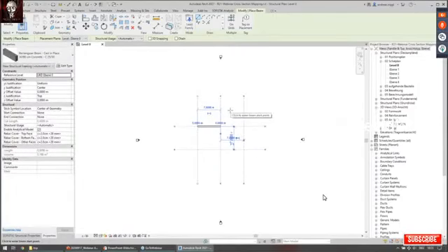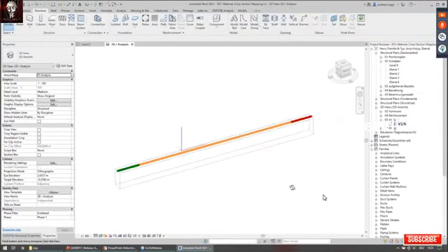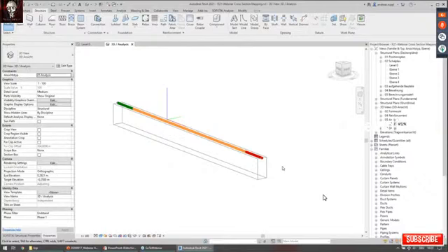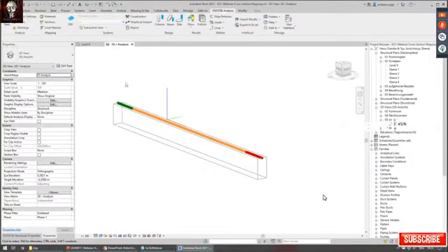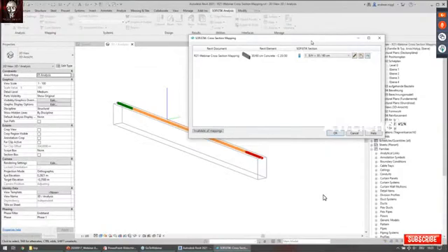So this is a predefined family which is present in the families provided by Revit, for example. And when switching to a 3D analysis view, you already see that beam within the structure model also. And as already said, when exporting the system the first time, or when clicking on this section mapping tab, the SOFiSTiK software analyzes the geometry of this Revit element and tries to map an appropriate SOFiSTiK section for analysis.